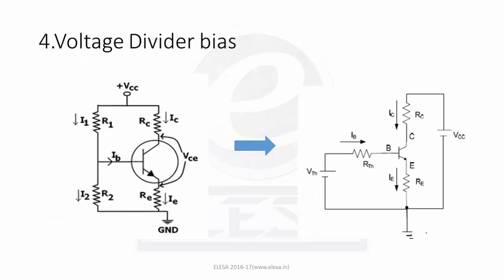So in this circuitry, see here how the emitter bias resistor RE fights against the instability of beta. That is, RE provides stability in the gain of the emitter current of a transistor circuit. Its gain amplification factor can vary by large amounts from transistor to transistor, even if they are the exact same type from the same batch. There is no replication of the exact same beta across transistors. Therefore, we have to design a transistor circuit where we want roughly the same gain. For that, we need the RE resistor.